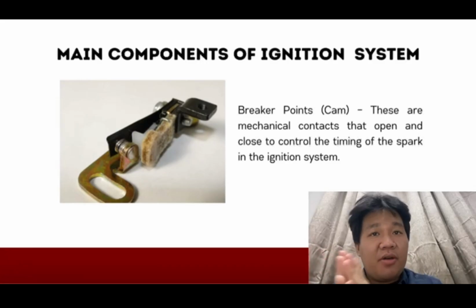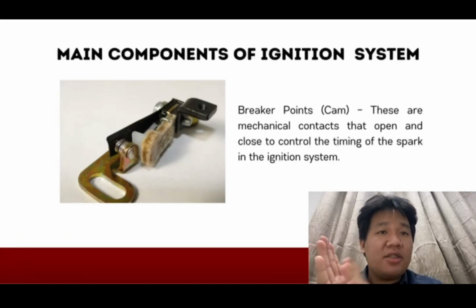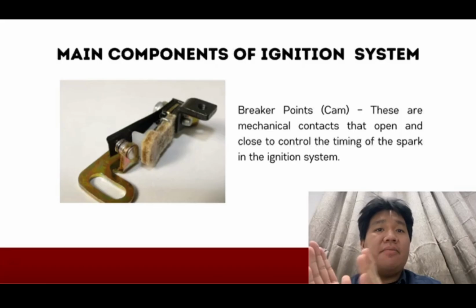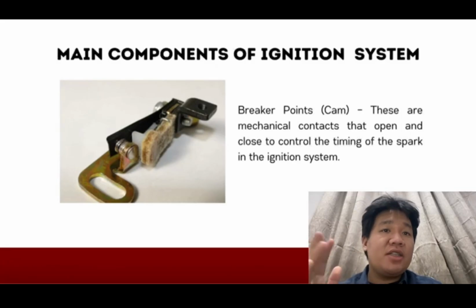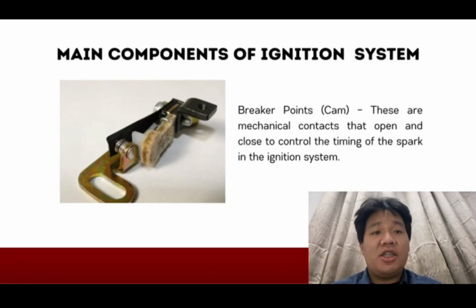The breaker points open and close to control the timing of the spark, while the cam makes the breaker points move at the right moment for each cylinder.